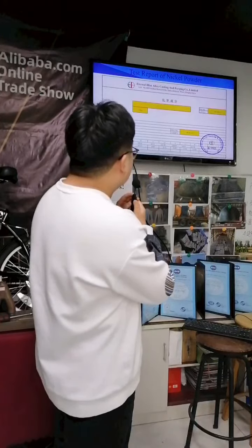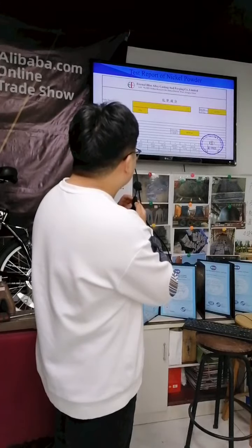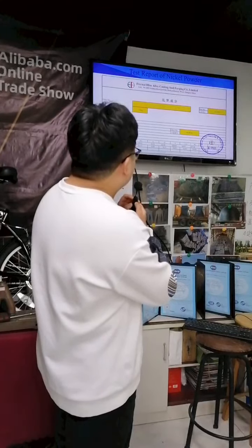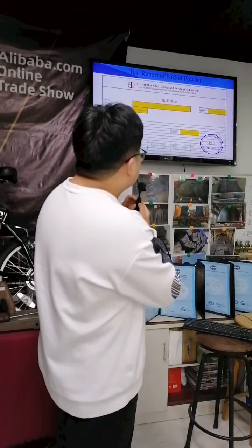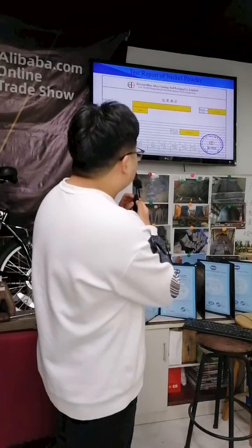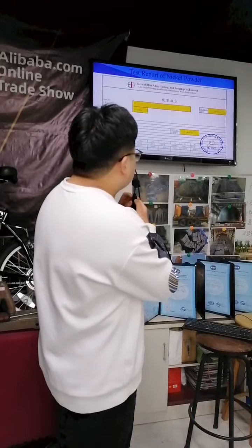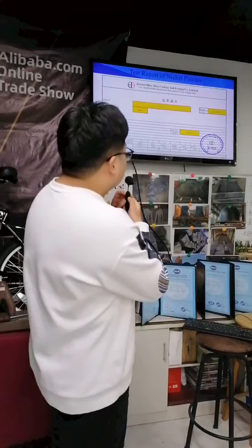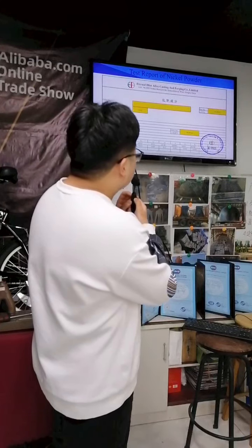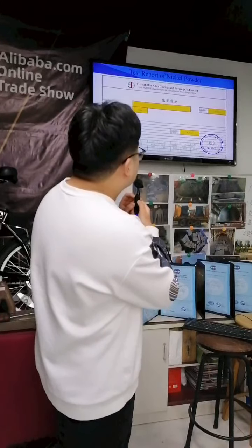The nickel is more than 99.0%. The carbon is less than 0.1%. The oxygen is less than 0.13%. The sulfur is less than 0.001%. The cobalt is less than 0.001%. The iron is less than 0.001%.